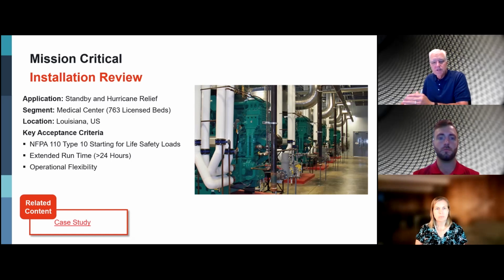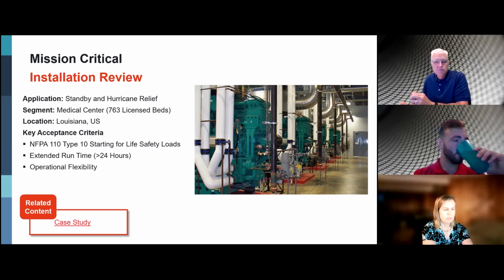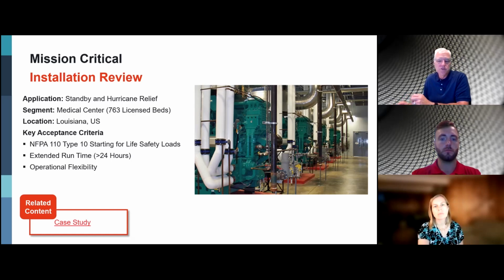At power failure to the normal side of the hospital, all 6 of the generators receive a signal to start and close to the common bus. The diesel will, of course, close first and supply the power to the life safety loads. The remaining 5 gensets will sync to a live bus and supply power to the remaining hospital power grid connected